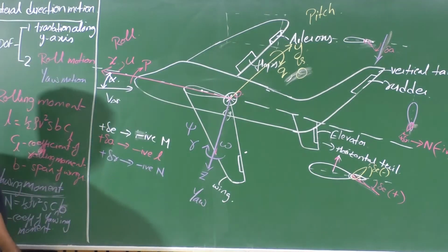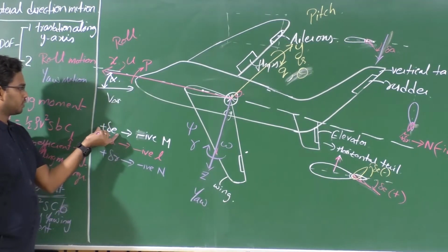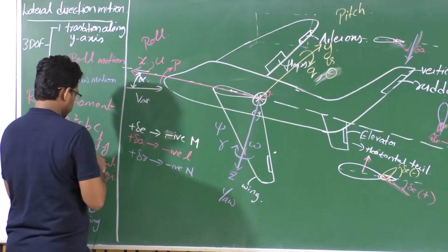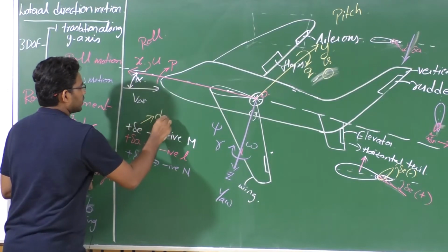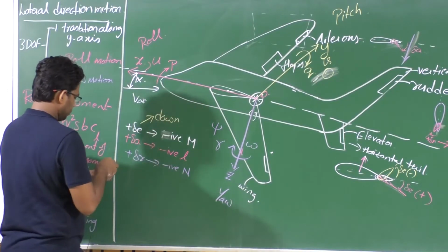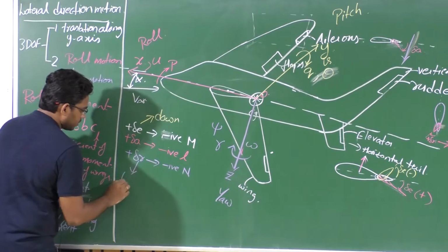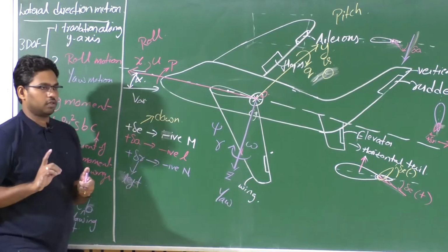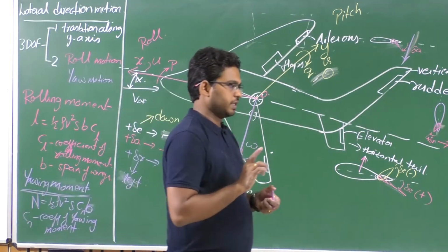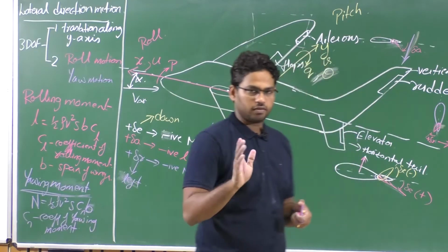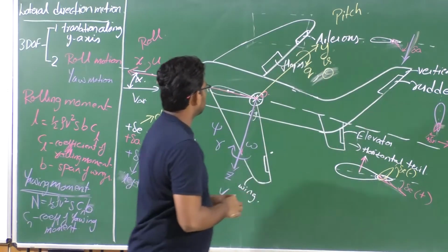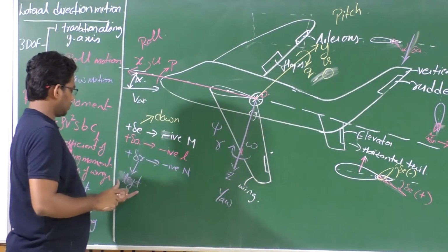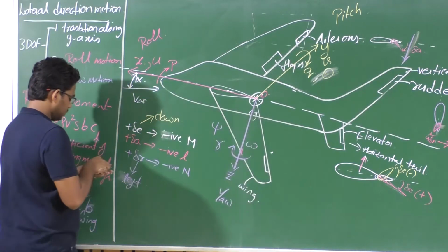Isn't it? So what is positive elevator deflection? Deflecting it down. So the corresponding positive deflection is deflecting it down, right? So here it is towards the left. When you are facing the aircraft from the tail, the corresponding rudder deflection towards the left side is considered positive. Right?